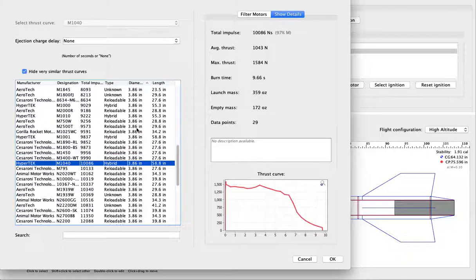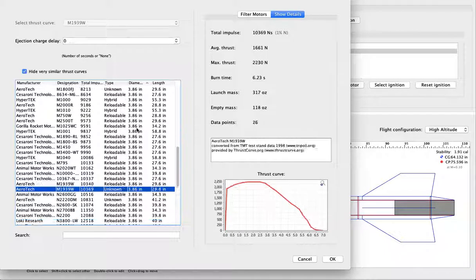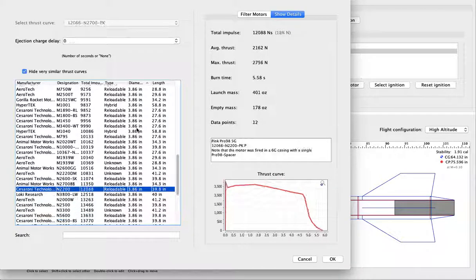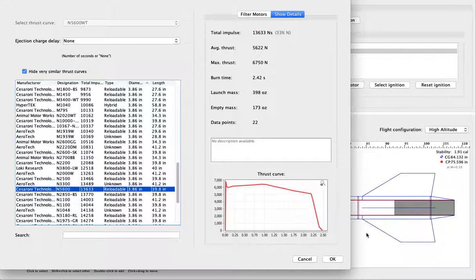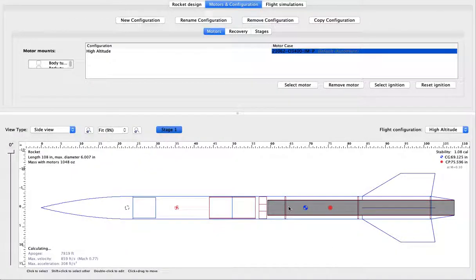All right, so you've also probably noticed this thrust curve. Now, this is dependent upon how you cut the grain, which we'll see in OpenMotor or BurnSim or whatever. But the most thrust isn't really all you want all the time. If you get right off the pad just absolutely blazing, you may kill your rocket because you're going Mach 4 with some horrendous acceleration so low in the atmosphere that everything rips apart and you don't get anything back. Well, you do get your rocket back, but you get 30 pieces of it. So we're not going to do that.